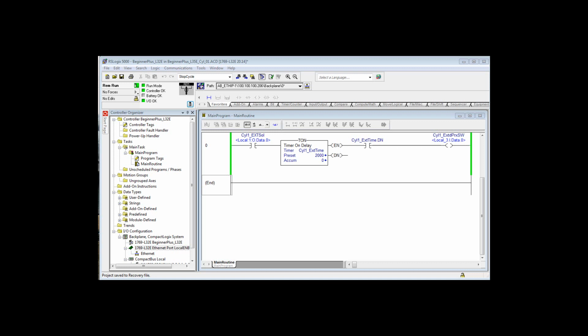So look at what we have here. This is really simple. If the logic sees that you told the cylinder to extend, and remember, we don't have a cylinder. We don't have a solenoid valve. This is virtual. In your logic, when you turn on output 0, and it'll show up on your LED backed push buttons on your digital field device simulator, if that's what you're using, when that output comes on, it starts accumulating cylinder 1 extend time.